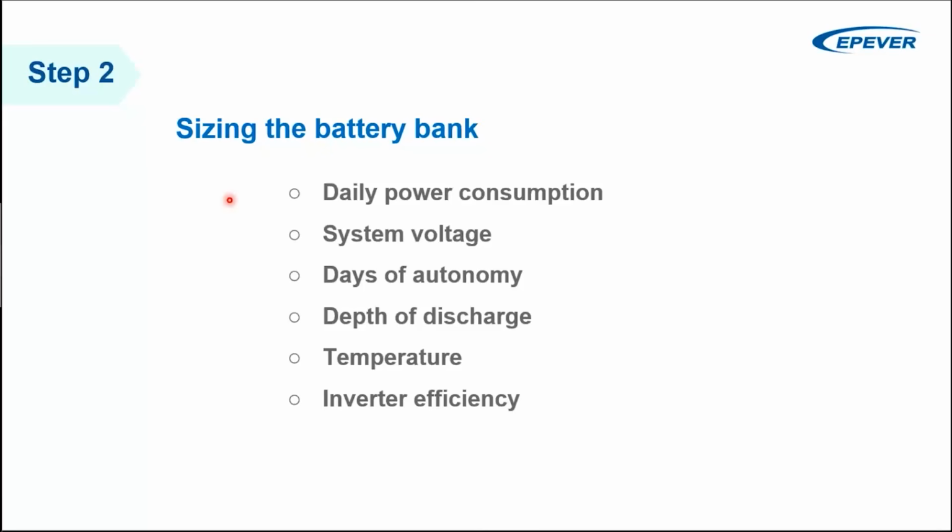So now that we know how much power we consume each day, it's now the time to determine the battery bank size. Here are the terms which determine the battery bank size. Batteries are one of the most important parts of every standalone solar system. Lead acid batteries and lithium batteries are the commonly used batteries nowadays in the market. System application, the budget, and expectations for the backup time are factors that play a role in picking the right battery type for you.